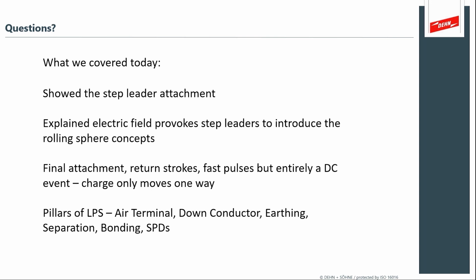So once it's in the ground, the master ground bar pigtail comes back up out of the earth onto your master ground bar. So the intent is to get the charge into the earth first and let it control and dissipate that charge. And that's why we talk about that ground potential rise. You can't get rid of the charge without it talking a little bit.